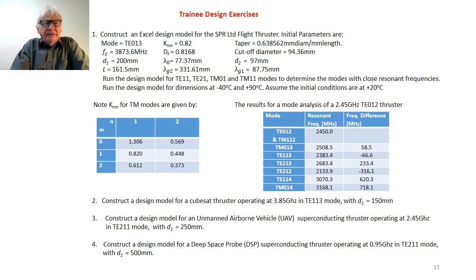Now, having confirmed to yourself that you have indeed produced your own Excel design model, what I suggest you do is run the design model for different modes. And this is important. A modal analysis is important for any practical design to make sure that you don't inadvertently end up with resonant frequencies for different modes that are too close to the design frequency that you're going for.